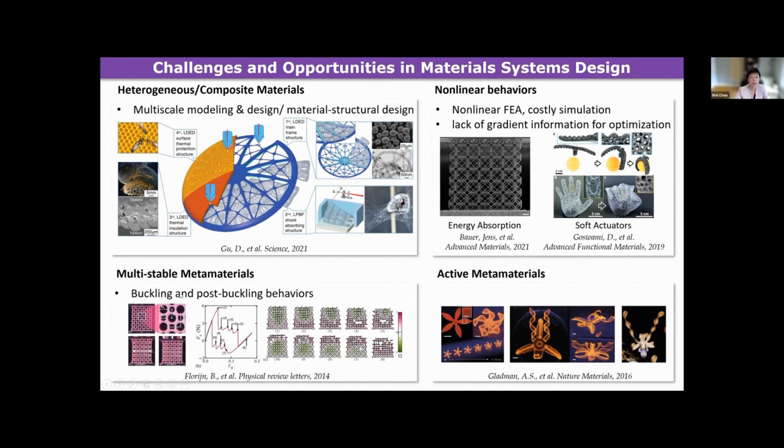A multi-stable metamaterial is a very tough problem because you have to handle both buckling and post-buckling behavior, which create nonlinear, discrete phenomena. Most of our methods can only model continuous phenomena. And active metamaterials add another dimension of complexity.